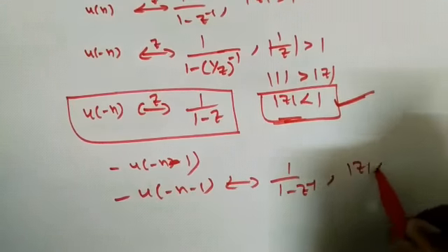What is the z naught here? Z by z naught is e power j omega naught, so e power j omega naught power minus 1. If I simplify this, it will become 1 by 2 into 1 minus e power minus j omega naught into z inverse. Yes or no? See, e power j omega naught is coming out of the numerator, so minus minus will be plus. So it is e power j omega naught into z inverse. This is the first part.